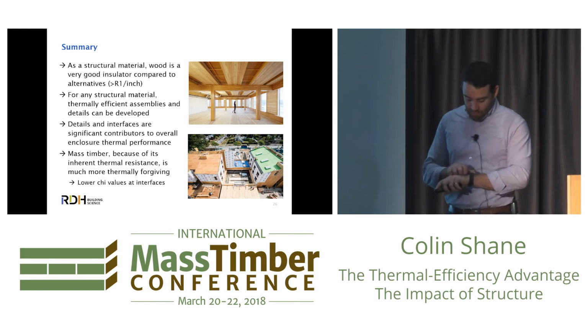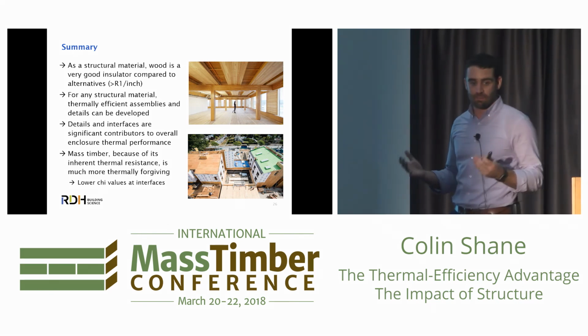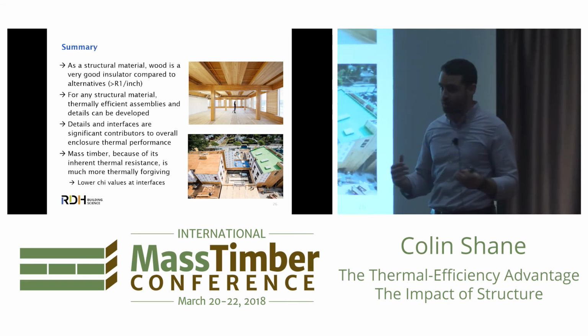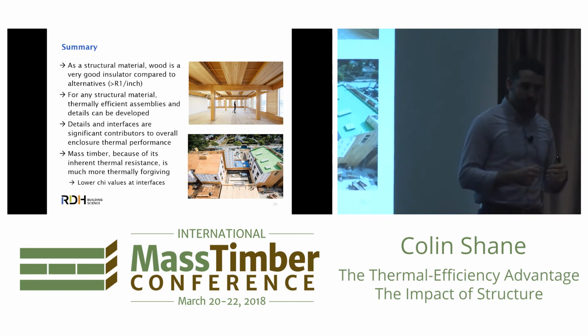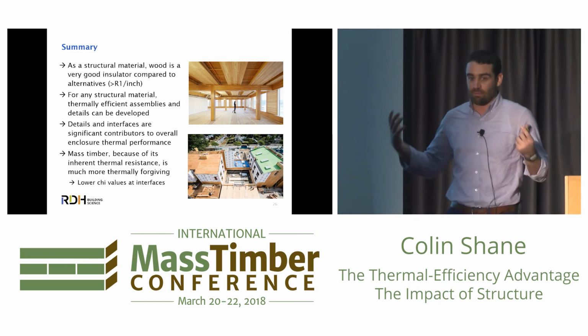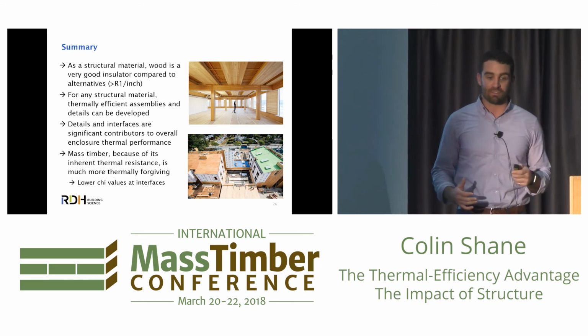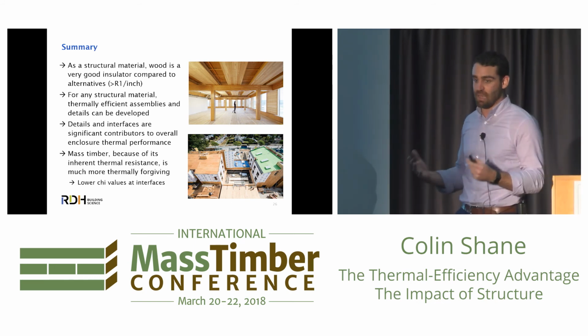All right, so wrapping this all up, as a structural material, wood's a good insulator. It's one of the nice things. There's a lot of good properties of wood, carbon sequestration, the fact that it's renewable and we can grow it. From a building science, from a building enclosure perspective, the fact that our structure is a pretty good insulator at the same time is really nice, and it helps us especially at interface details.